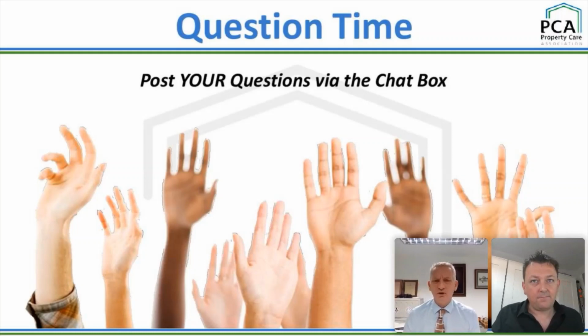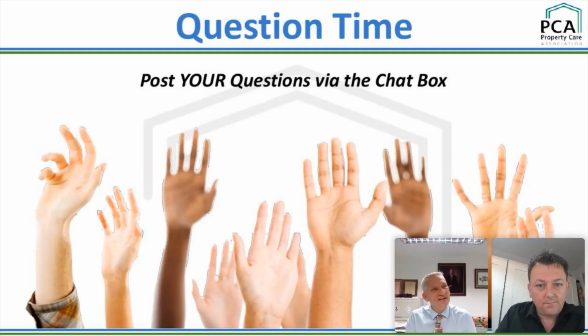If there's a crack in a wall, then generally speaking, okay, well, why is it cracked? That's the first thing. So let's assume in this case, we know it's just nothing. It's just a small little bit of settlement, a tiny bit of thermal movement, and there's a crack. There's nothing to stop you just monitoring it. In fact, there's nothing to stop you raking it out and pointing it up and doing nothing as long as you can monitor it, you know.